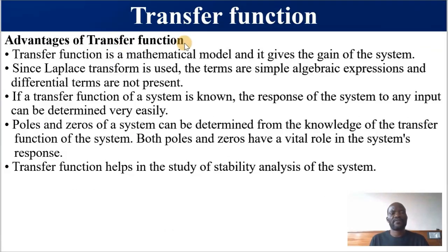Advantages of a transfer function. The transfer function is a mathematical model and it gives the gain of the system. Remember your gain, the ratio of the output to the input. Since the Laplace transform is used, the terms are simple algebraic expressions. It is easier to solve algebraic expressions since we are not using differential terms. Third, if the transfer function of a system is known, the response of the system to any input can be determined very easily. We are going to experience this.